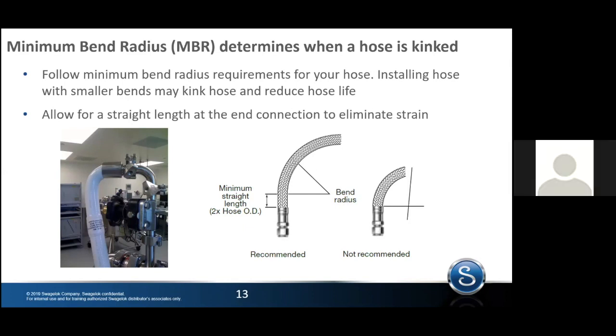Okay, and a second question, how do you properly implement a preventive maintenance program in your facility? So what we have done is the first step obviously is to start cataloging the hoses. Where the hoses, give it a name, put a tag on it, start tracking that in an Excel sheet or whatever form you would like, and mark the install date, and start documenting things that the hose will see on a regular basis.